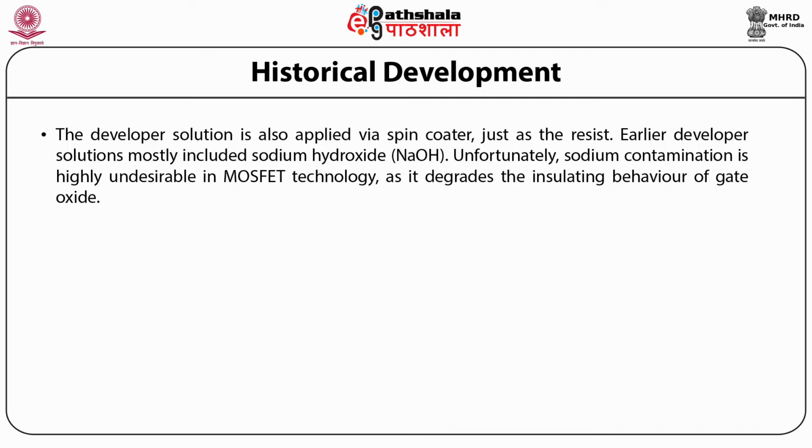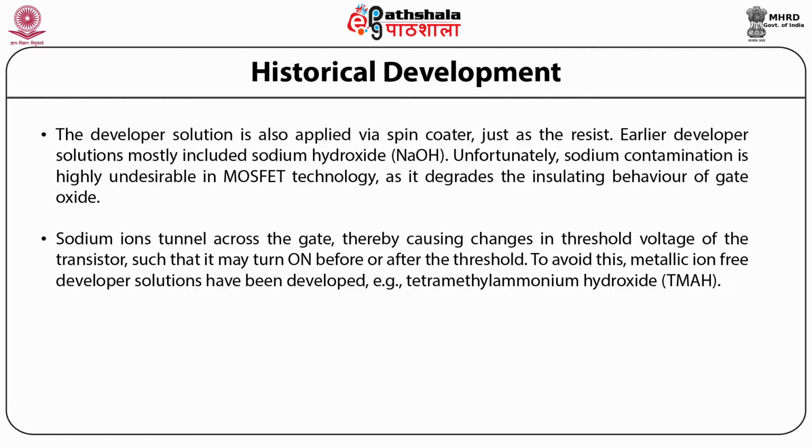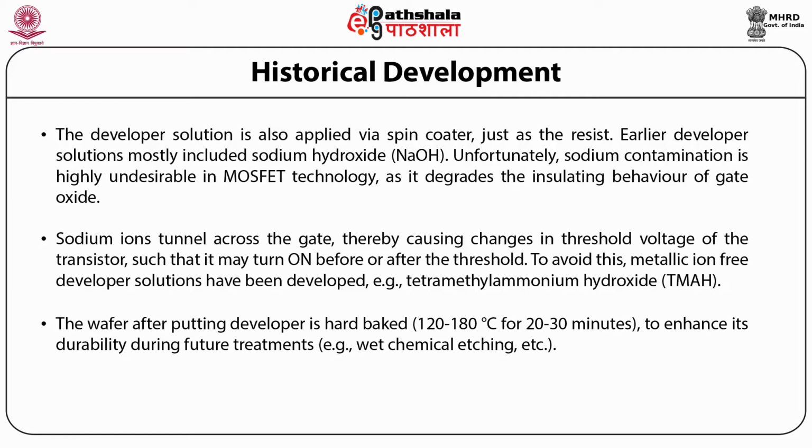The developer solution is also applied via spin coater just as resist. Earlier developer solutions mostly included sodium hydroxide. Unfortunately, sodium contamination is highly undesirable in MOSFET technology as it degrades the insulating behavior of gate oxide. So, sodium ions tunnel across the gate, thereby causing changes in threshold voltage of the transistor such that it may turn on before or after the threshold. To avoid this, metallic ion-free developer solutions have been developed using tetramethyl ammonium hydroxide. The wafer after developing is hard baked to enhance its durability during future treatments.